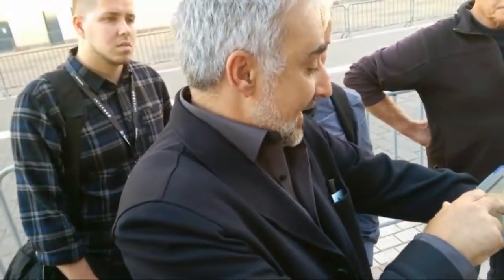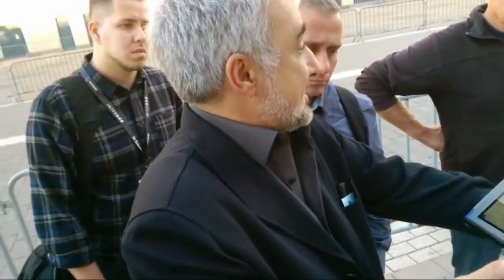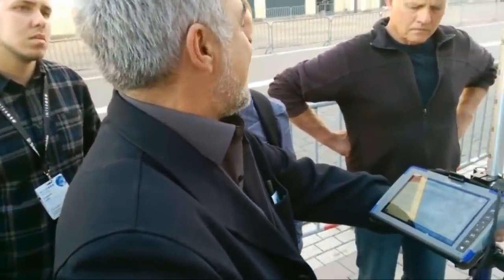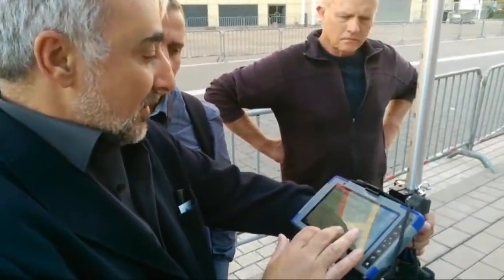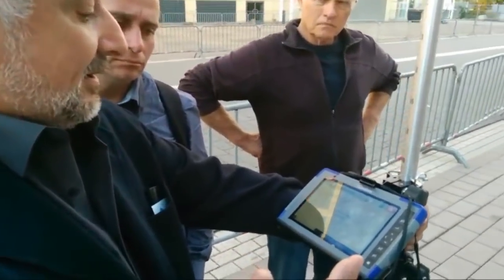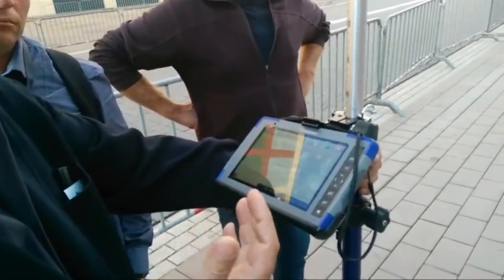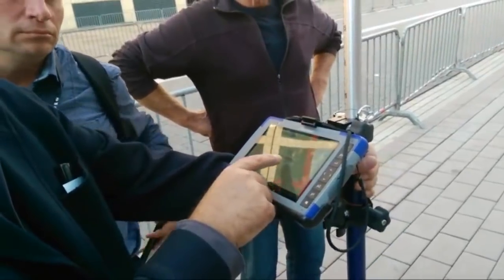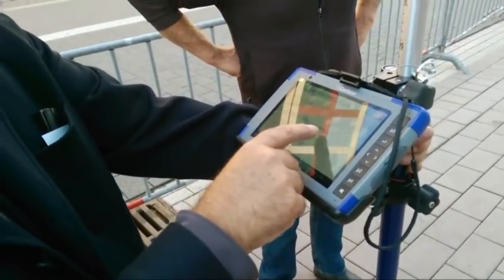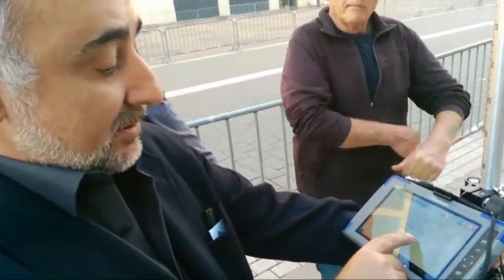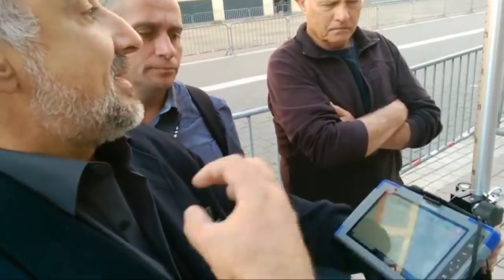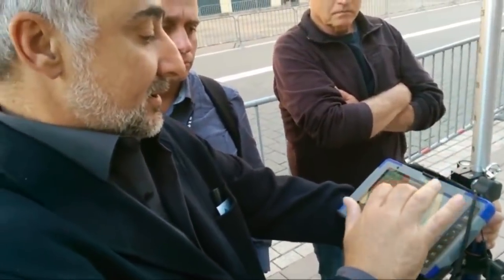It's okay. Then I perform a cross check. In land surveying, you need to be checking all the time to make sure you're doing things right. So let's do it, because I'm combining the two. I need to trust I'm doing right. Okay, so this is the check. Distance error 8 millimeters right now between the GPS and the total station. Elevation error 10 millimeters. It's good. It's acceptable. It's within my tolerance, so I'll go ahead.